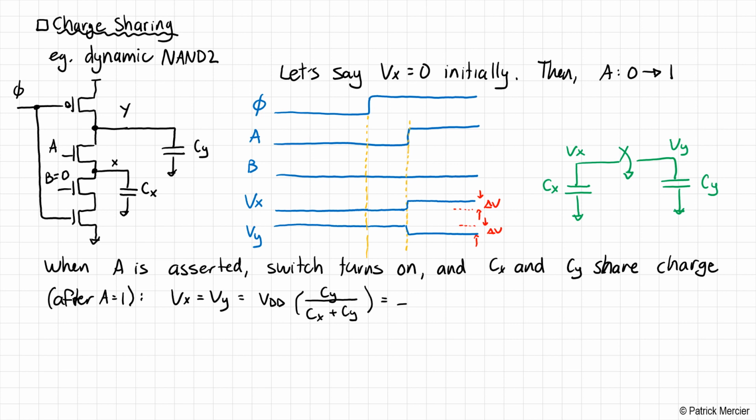And we're going to say that's equal to delta V. Okay, let me put a little asterisk here and just say careful if V out ends up becoming less than VTN, because then we have a threshold drop across the NMOS device, and this formula isn't totally correct because it's no longer acting as a good switch.